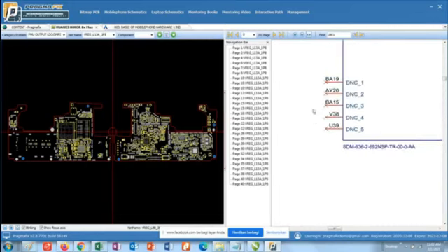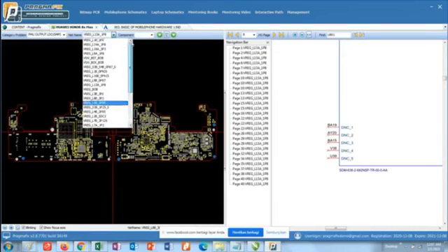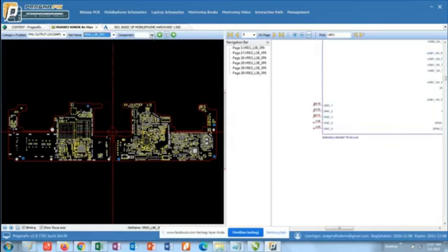The processor needs RAM, needs eMMC or ROM, or for example uses UFS. Yes, it must be met first from the power side. If the IC fails to distribute to one of the needs of the three components, then the mobile phone will fail to boot to the next stage. So, the LDO output voltage, yes, we just look at an example.